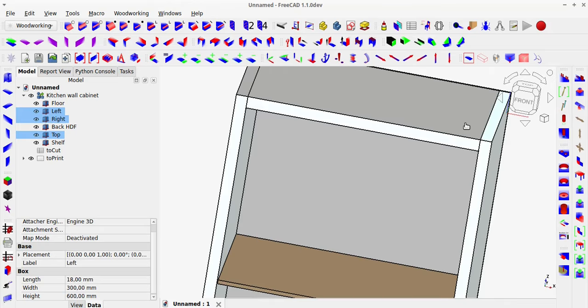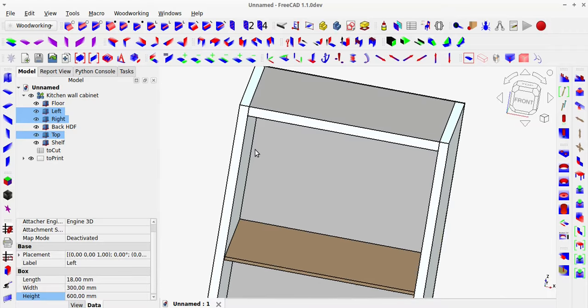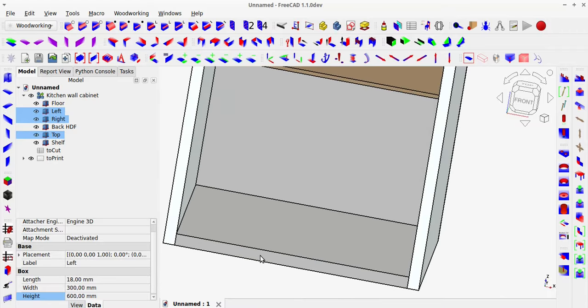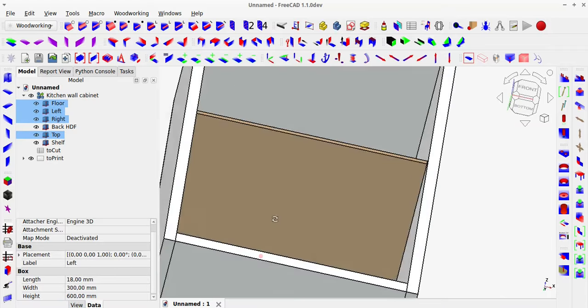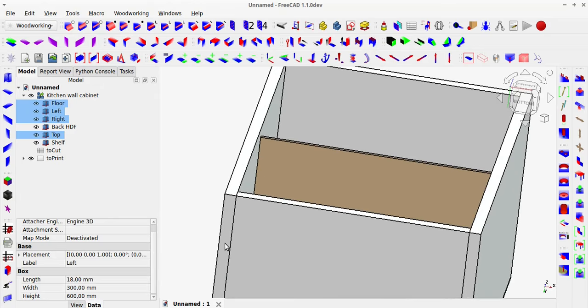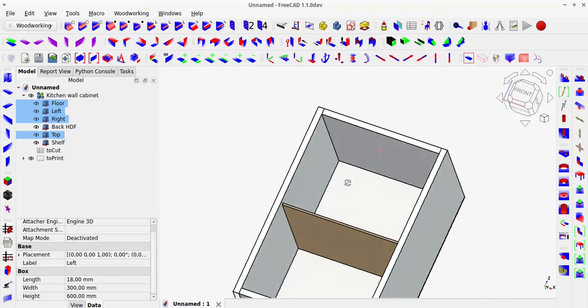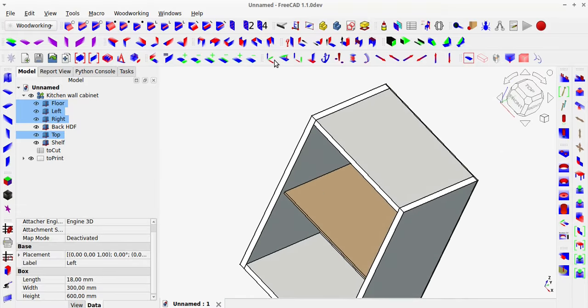Personally, I often add black veneer to 18 mm white chipboard furniture. And for 6 mm plywood shelves with a removable interior, I add white veneer to the front edge. This makes the shelf look much cleaner and nicer when opened.